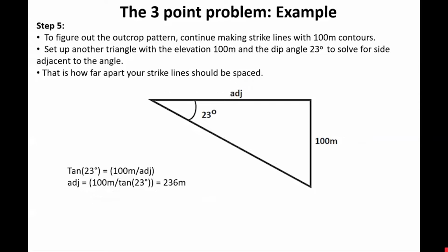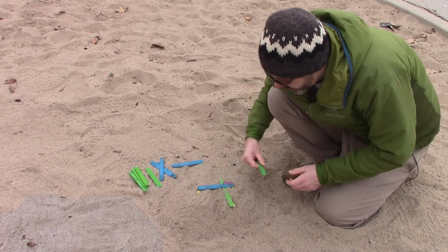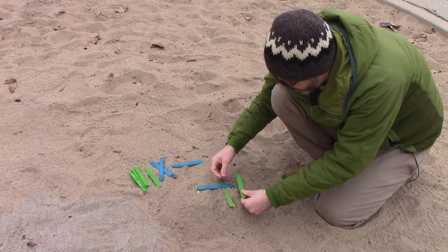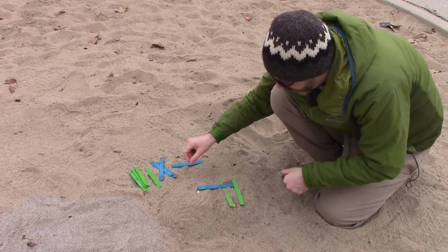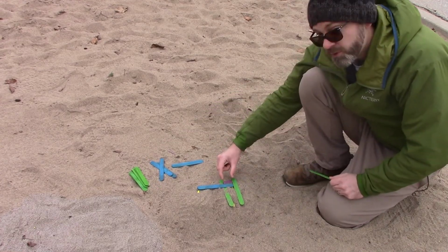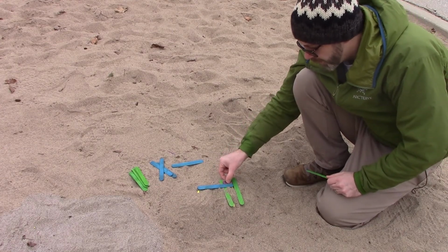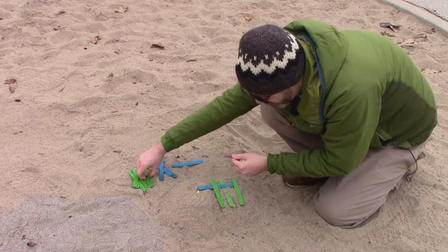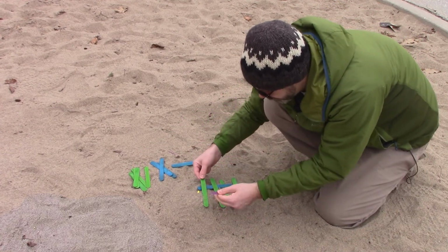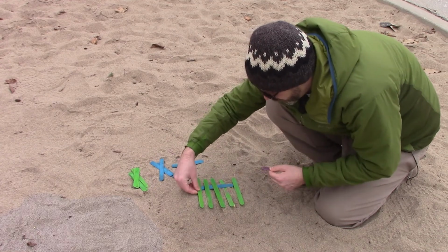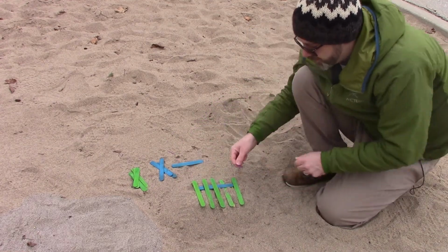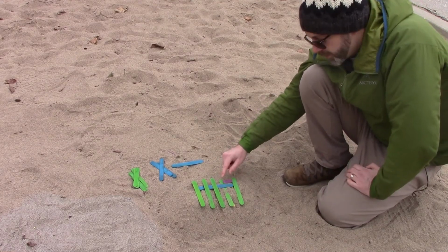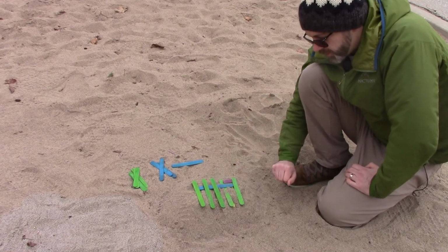So now the next step is to figure out where all these structure contours should exist. So we can actually repeat that with multiple green lines. So we're going to have parallel green lines equally spaced horizontally the same length as this purple line. So that would be here, along there, another one there, another one like that. So each of these then represent the elevation of the plane in space, and they're slowly going uphill there.